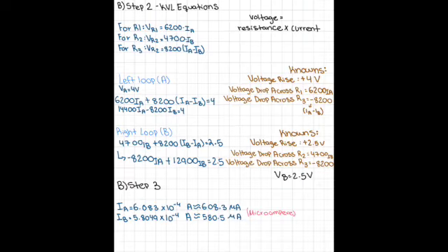Thank you. Hello everyone, my name is Angie Reyes and I will be doing section B. I will be explaining how I got the KVL equations for the circuit. Before writing KVL, I first rewrote our resistor voltages using Ohm's law. Since we need each resistor voltage in terms of current, we will use voltage equals resistance times current, leading to the following equations. This last one has two currents because it is shared by both loops.